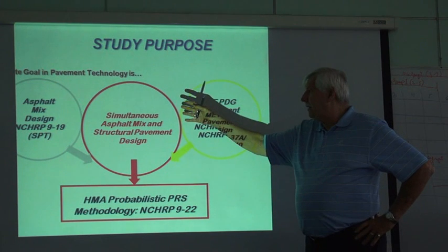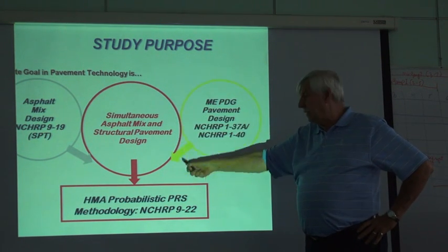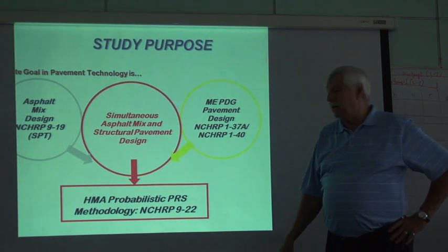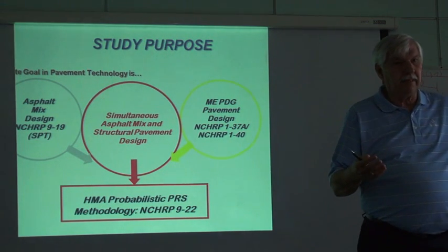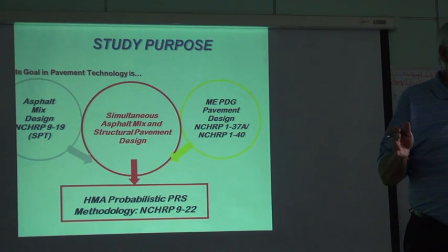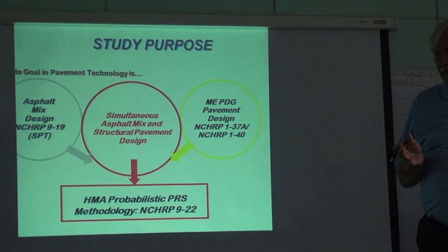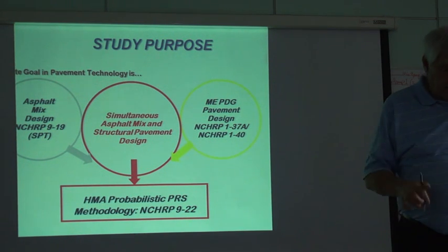What has been done is to merge these in the 922 technology to come up with a probabilistic performance-related specification. I'll show you in just a moment. I won't get into a lot of details, but this is not only a mechanistic-based, fundamental asphalt mix design, but it relies heavily upon probabilistic solutions and analysis in looking at pay factors.